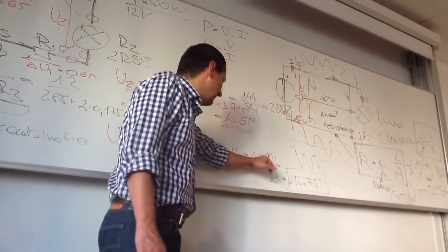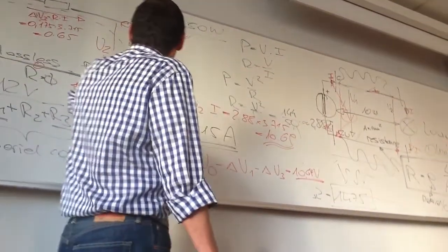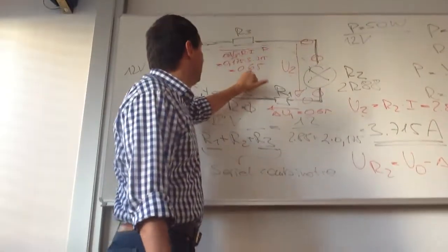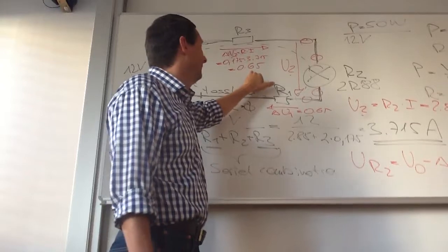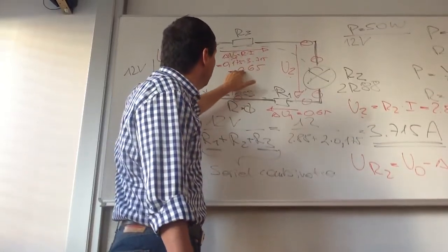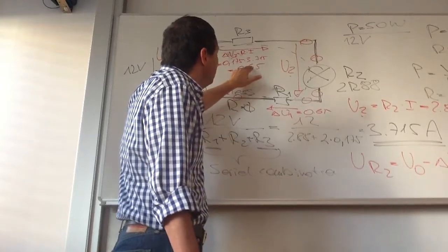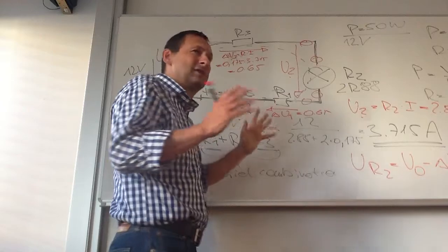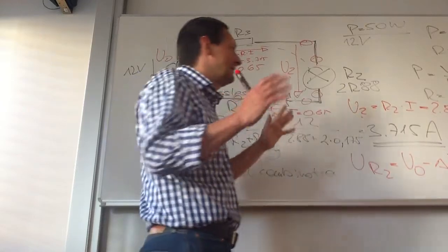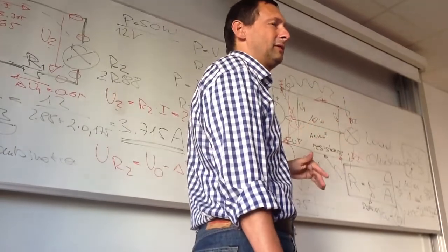So there is no 10.7. It was only a guess. Because I doubled the voltage drop here, it's 1.3. Yeah? But actually we will not see 0.65, it might be 0.58 something. Yeah? So that's a calculation error. That's not an error in our circuit or in our thoughts, it's a calculation error.